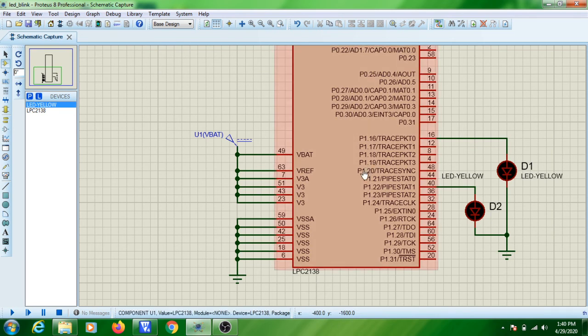Right. So now I have configured the program, the clock frequency, the crystal frequency, and the VCC. I have connected the LED. Then the next step is you need to start the simulation. For that, on the left hand side bottom you can see an icon known as run the simulation. Click on that. When you click, you can see that your LED will be blinking, at whatever rate you have configured.